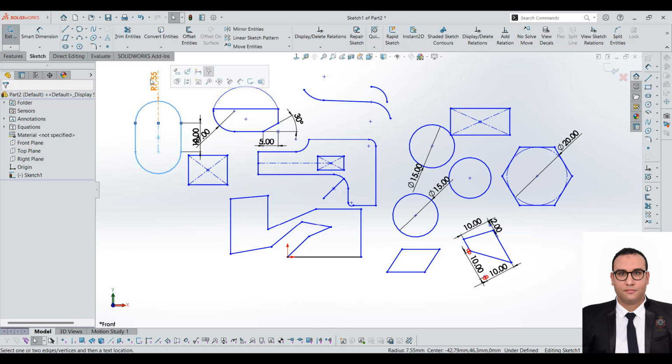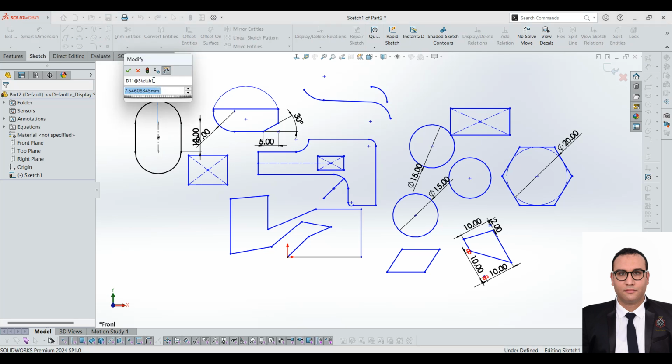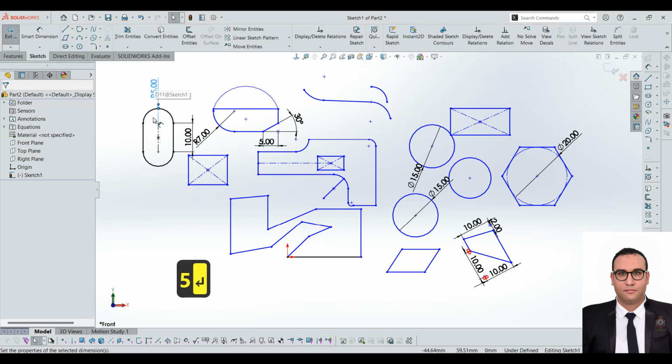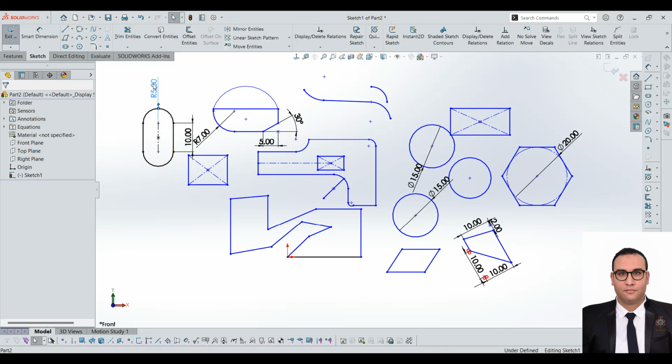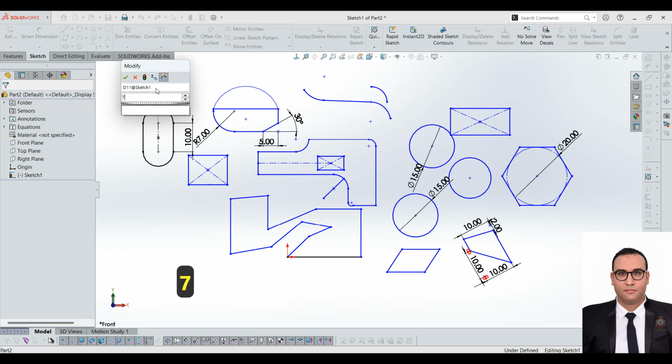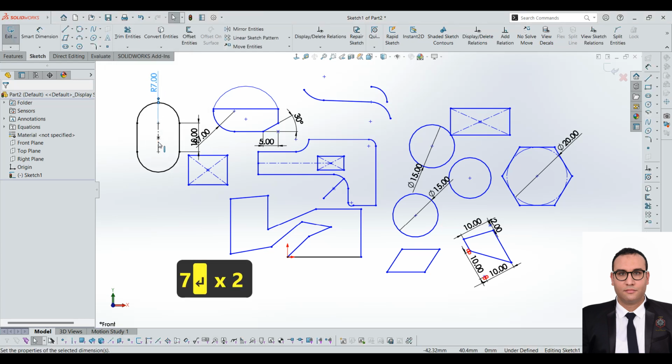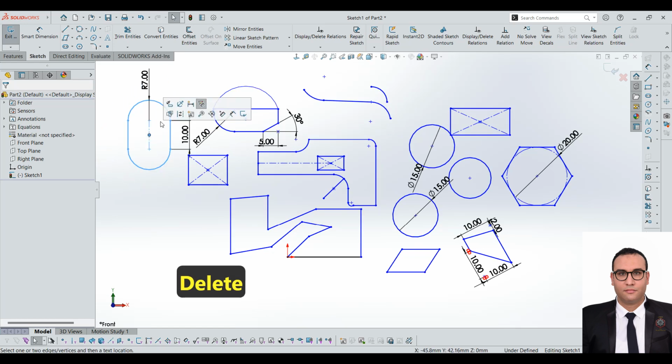When you push this, it will appear. The 5, for example. That dimension we can choose at any time by clicking it 2 times. For example, 7. No problem at all. If we remove the fixation right here, it will be free again. See? And we can fix it with this one to fix it all. This will fix a point. This will auto insert dimension.